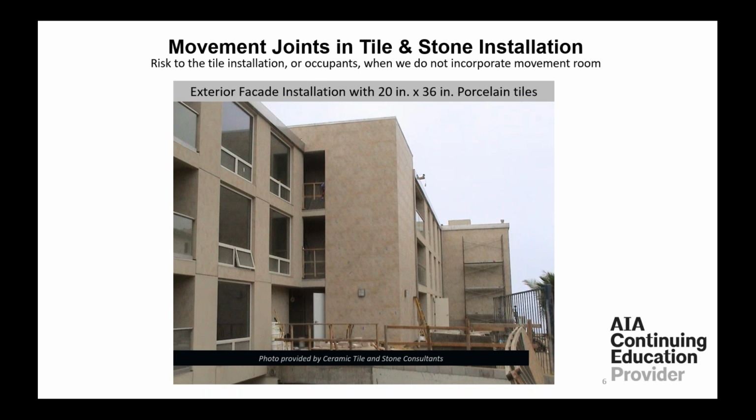We'll get into a lot more about movement joints, sealants, and so on as we go into this presentation, but it has to be clean. It has to allow for the tiles to expand and contract and/or the substrate.